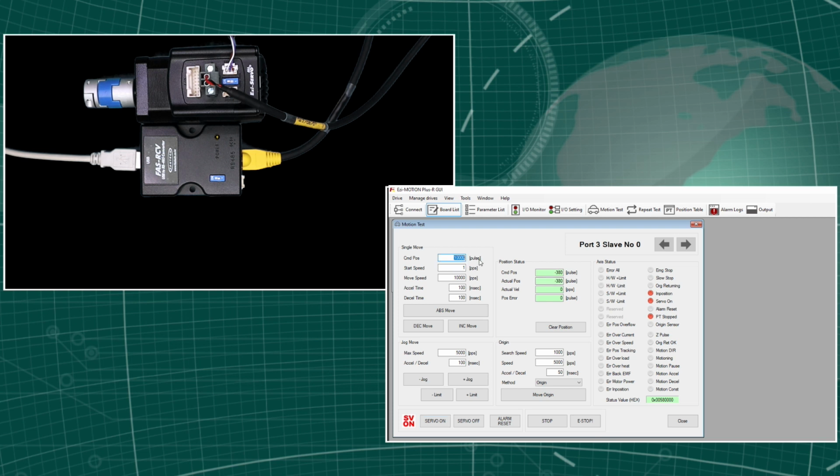I will try to move this command position to 0. Therefore I set that it should make 380 steps, and then I can move into different directions, and you see that the coupling is always moving 380 pulses. Now we have a command position of 0 and also an actual position of 0.